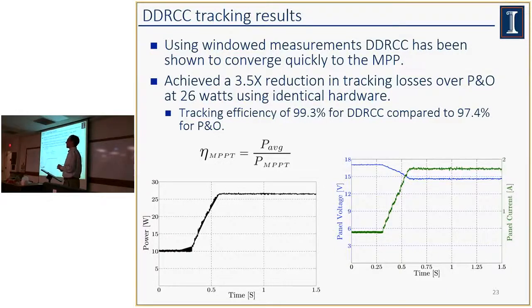Well, but you have to consider the relative value of the noise compared to the native resolution of the ADC. So if under these noise conditions, the minimum realistically achievable resolution may be the same with a 12-bit ADC as a 10-bit ADC, depending on how that worked out. So I'd have to think about that a little bit more, but you could end up in the same place.